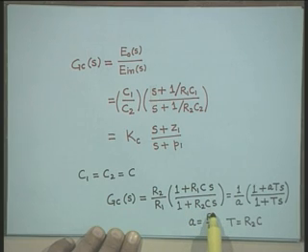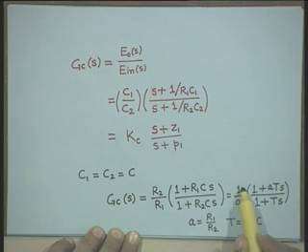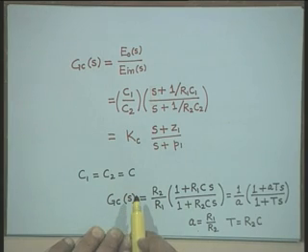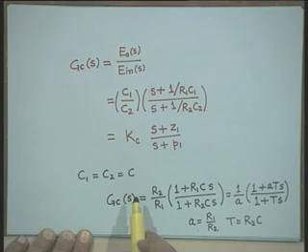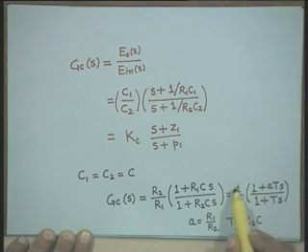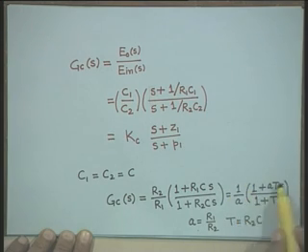R2/R1 can be written as 1/A, where A = R1/R2, and T can be written as R2 C. Therefore, I now get the transfer function of the compensator in the form (1/A) (1 + A T s)/(1 + T s).